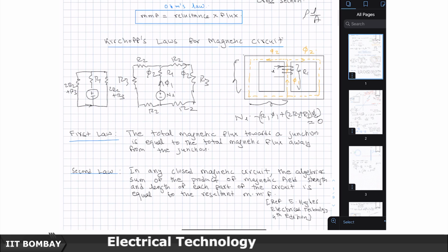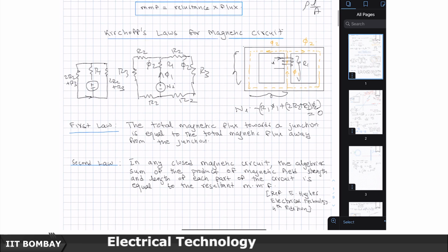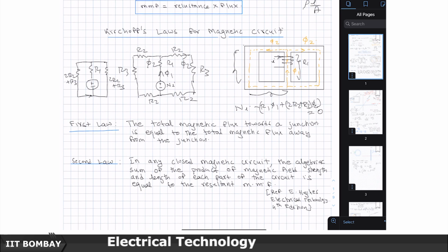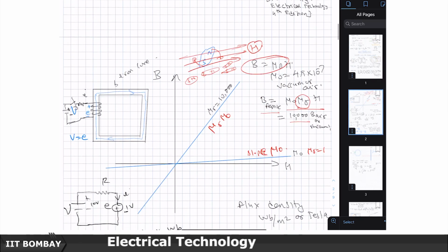So, with this, I think you would really appreciate that this is a beautiful simple way of treating magnetic circuits, reusing the knowledge of what we have in electrical circuits.